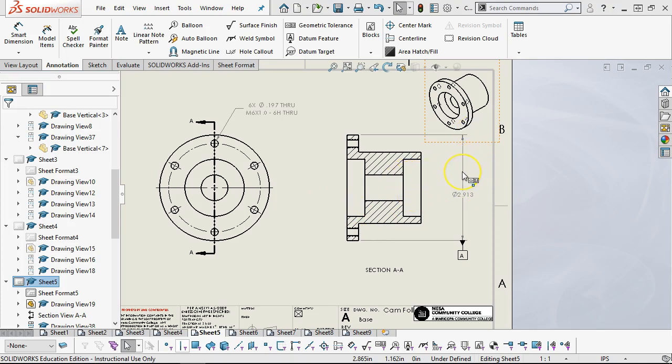Right? We made the perpendicular, since whatever we said, 2 kilogram mass rotating out there off center is all hanging off of that shaft. We wanted those to be fairly tight geometries. Have the positional of the keyway be able to open up so that it doesn't have to be as tight to fit through the cam, but still take care of all the tolerances. So still thinking about that one. I'm fairly satisfied with the shaft being the A datum, because that's what has to line up and go through the 2 bearings centered in the housing.